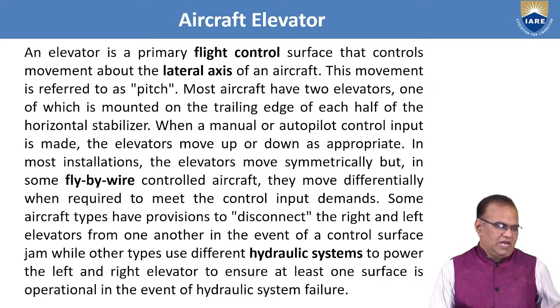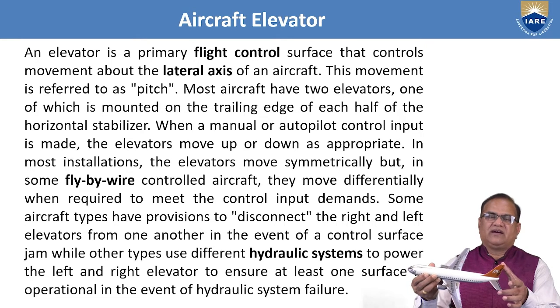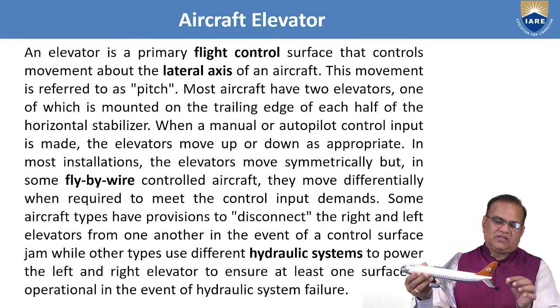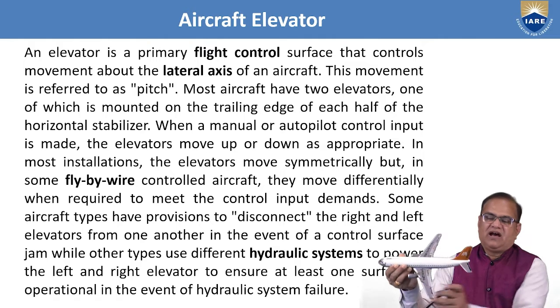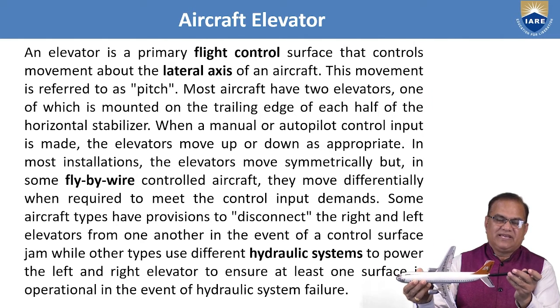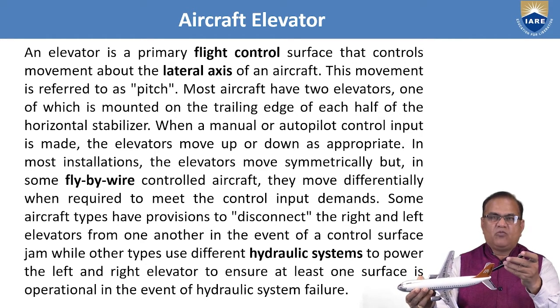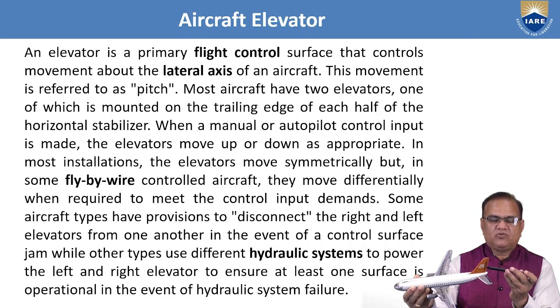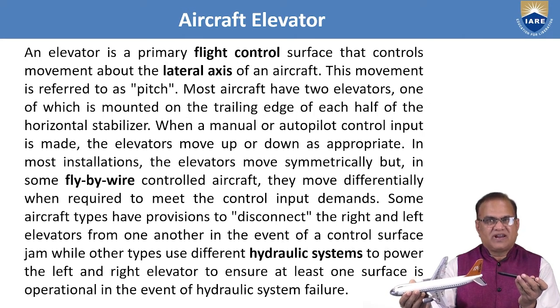Okay, so I can show this here. When I talk about the longitudinal control, at the horizontal tail you can see the black color. This black color here and here, these are the elevators, and this half of this side and half of this side can move upward and also downward as per the requirement of the condition.